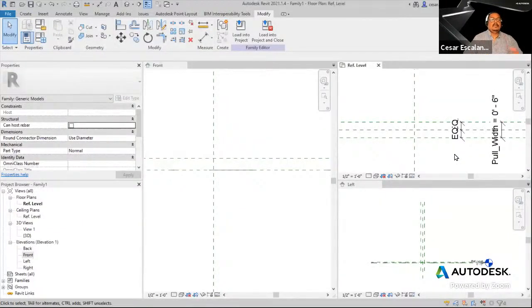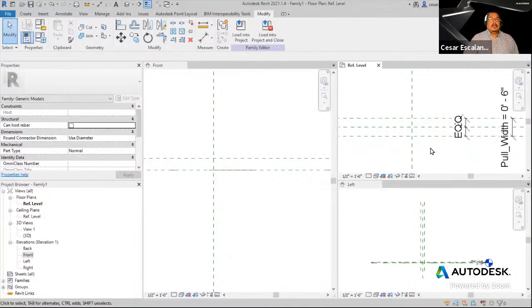What that means is that in Revit, remember that we can display objects in different resolutions, so you can have objects in coarse view and fine view. And in the family editor, we have the ability to display certain elements in certain views and disable them in other views. And so for the pool, a very simplified representation of a pool is just a single line.